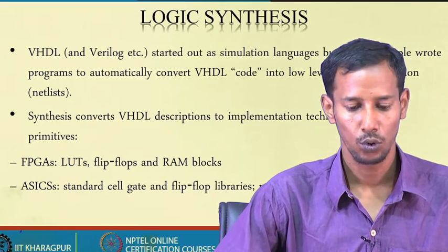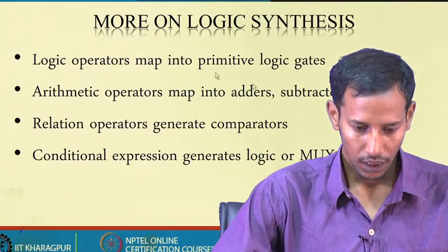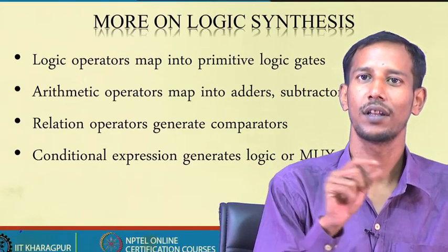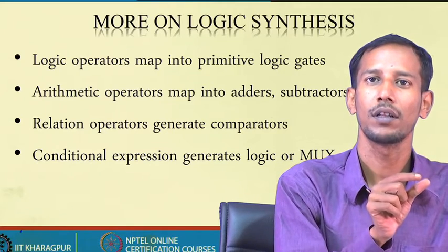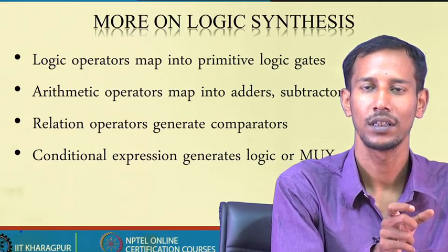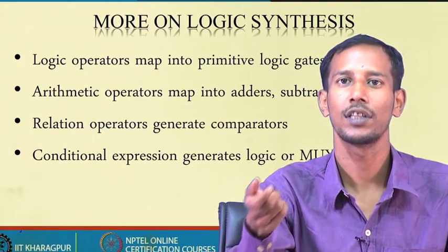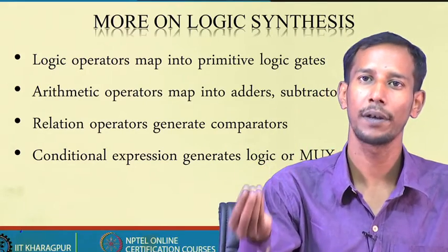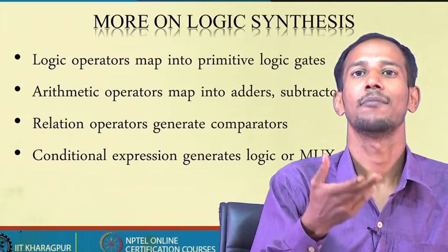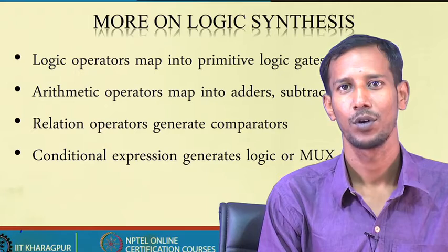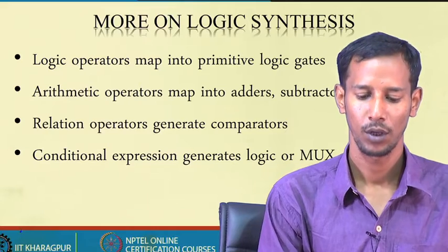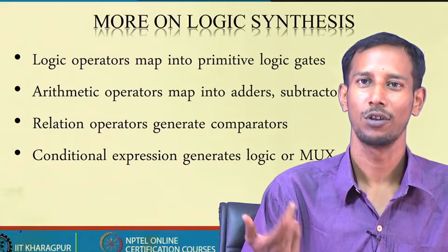Okay. So, you have this particular information in your library. Whatever logical expression you are describing using the HDL language, during the synthesis those gates or operators or memories will be called to implement your particular system or the expression which you have mentioned in the EDA tool. Okay. So, that is the process of logic synthesis.